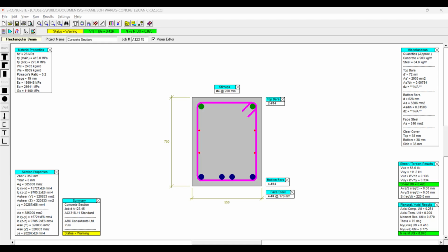their dimensions. From the structural analysis, the most critical values obtained were the maximum factored bending moment and the maximum factored shear force. For this project, the design values obtained from Module 1 were the maximum factored moment, Mu, equals 250 kilonewton meters, and the maximum factored shear, Vu, equals 180 kilonewtons. These two values became the primary design loads for the reinforced concrete beam.